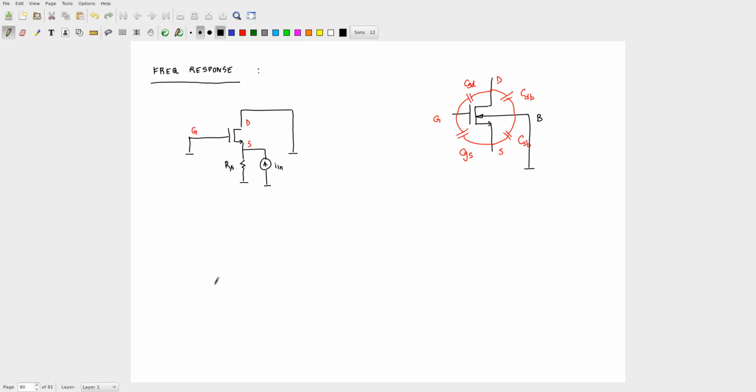Okay. So now that we have this particular incremental circuit, let's draw it in terms of the dependent source, and let's not worry about putting it in that horizontal picture. We'll have it in the vertical orientation itself. Okay. Gm times 0 minus Vx. This guy is your Vx, correct?